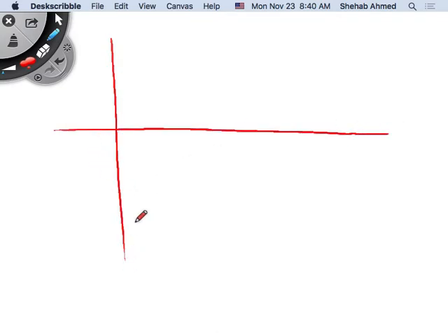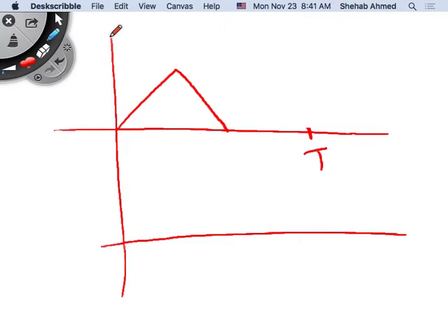In discontinuous mode, inductor current can look something like this during a switching period. This is IL. It goes down to 0 for part of the switching period. This is called discontinuous conduction. It has a very low average value, for example at a very light load.